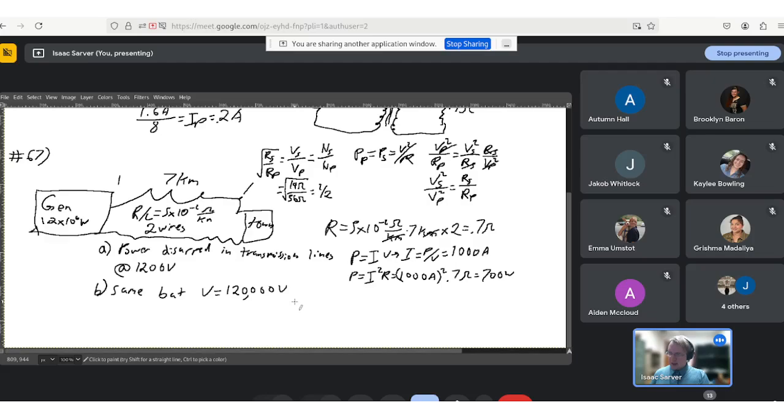All right, in this case, P equal IV implies that I, P divided by V, will give me, scroll up and put 2 more zeros into that, something that's 100 times smaller. So 1,000 divided by 100, that'll be 10 amps.